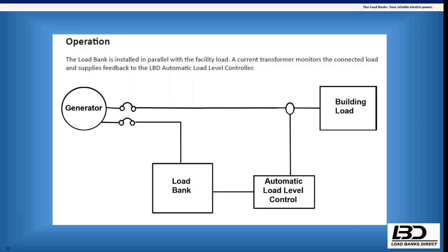Yep. As soon as you lose your 120 volt control power, basically the whole thing shuts off. There's no 120 to power any of the relays, contactors. It totally goes dead. So there's no chance of overloading there.